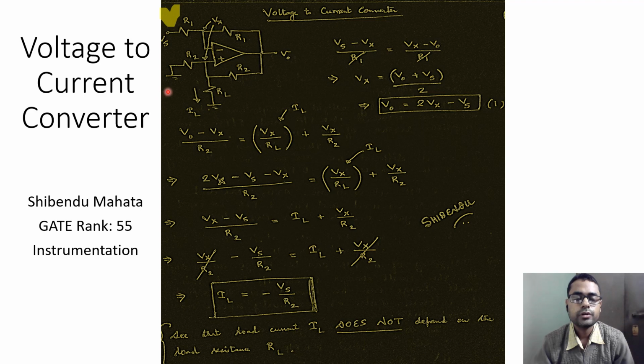So as before, whenever we are given some op-amp circuit and there are feedbacks present, we try to identify what will be the voltage at either this node or the voltage at the other node, whichever is the easier one to calculate. And because of the concept of virtual short, the voltage at this node, if I call this Vx, then the voltage at the other node will also be Vx. And judging by this particular topology, it is easier to look at the top branch, and we can easily formulate this voltage Vx.